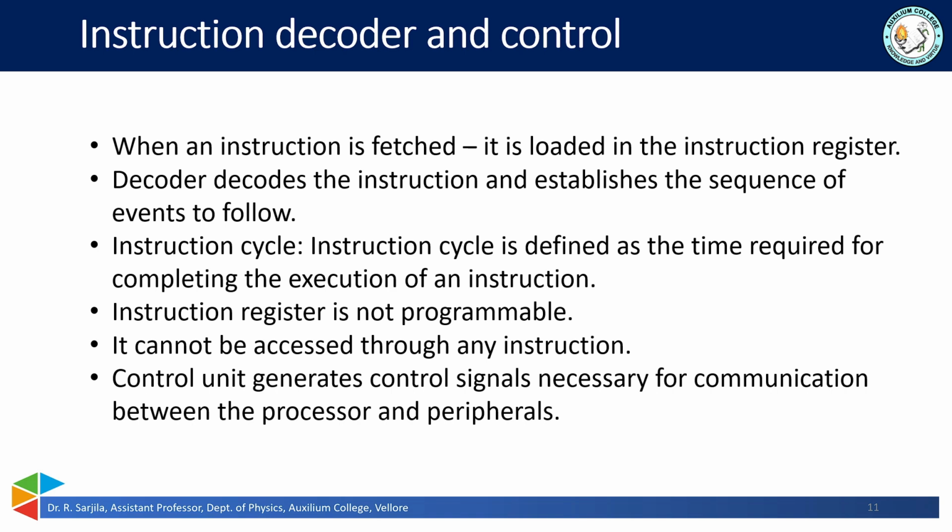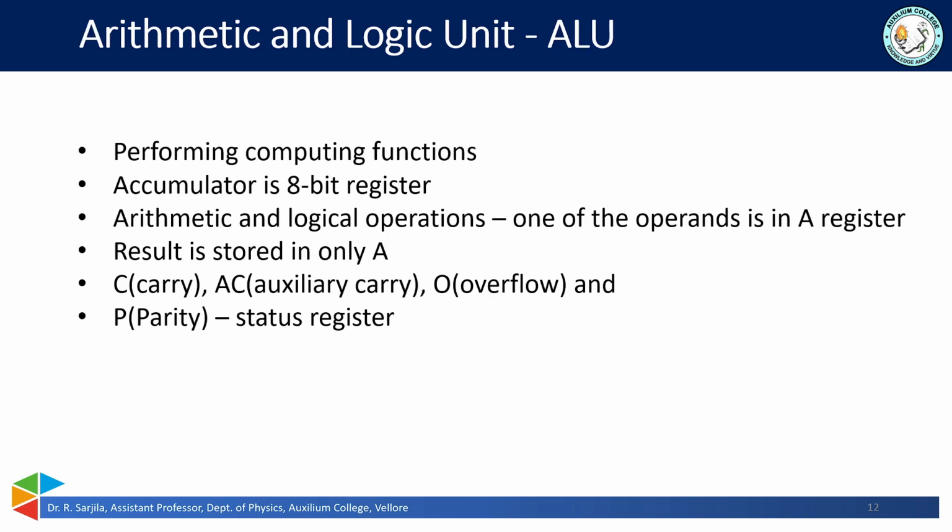This register decodes the opcode of an instruction to be executed and gives information to the timing and control unit to generate necessary signals for the execution of the instruction. ALU. The arithmetic and logic unit performs 8-bit arithmetic and logical operations over the operands held by the temporary registers TMP1 and TMP2. Users cannot access these temporary registers.